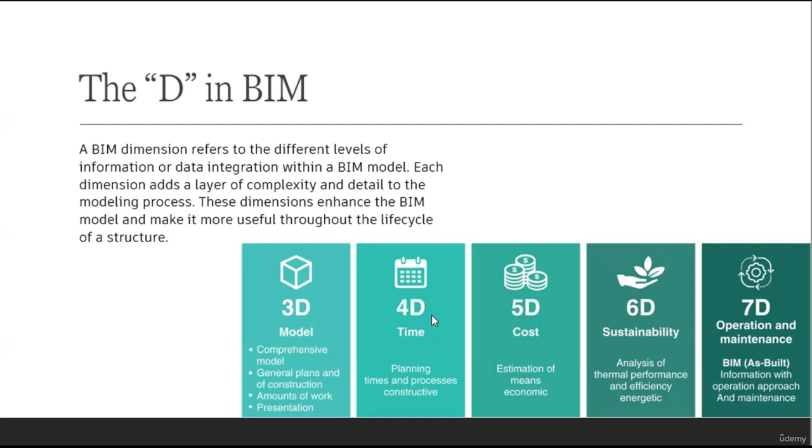Okay. The 4D deals with the time factor. Assigning time parameter to the existing 3D model will result in achieving a 4D model. The time parameter can be linked with the help of Microsoft Project, Primavera, or simply by using an Excel sheet. The 4D helps us over the traditional planning activities by adding a visual aspect to it. We can monitor the site activities on time basis and have a visual comparison between the actual and the planned work using the 4D BIM.